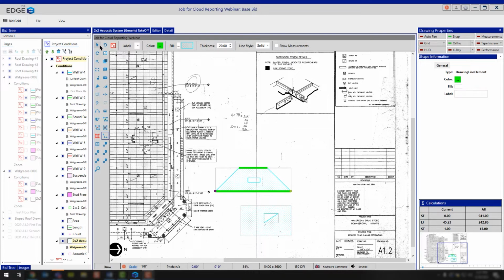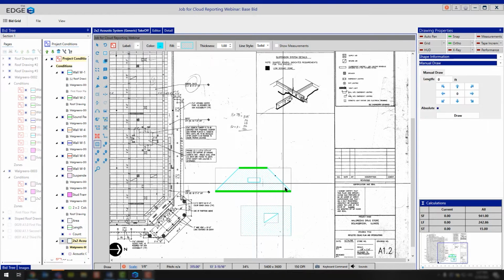The next tool you have is your room horizontal. So we're going to click on our trapezoidal shape, and this is the room horizontal tool. What you're going to do is you're going to click on that, and when you get your crosshairs, you're going to draw across the shape, and specifically one side that you want the grid to be based on. So in this case, the grid is based on the top line here. Let's say that I want it to be based on the wall angle. If that was the case, I've clicked my room horizontal, and now I click across that line, and you'll notice that it relayed out the grid here.